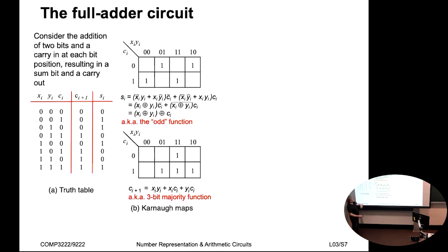All right, let's turn our attention to the carry. In the top half here we see the AND and in the bottom half we see OR. But that's if we use xi as the variable that we're factorizing around. Let's not do that. Let's have a look at when we map this into the Karnaugh map, 0, 0, 0, 1, 0, 1 over here, and then 1, 1 here, then we can combine each one with its neighbour, thereby having a slightly simplified expression that we have down here.